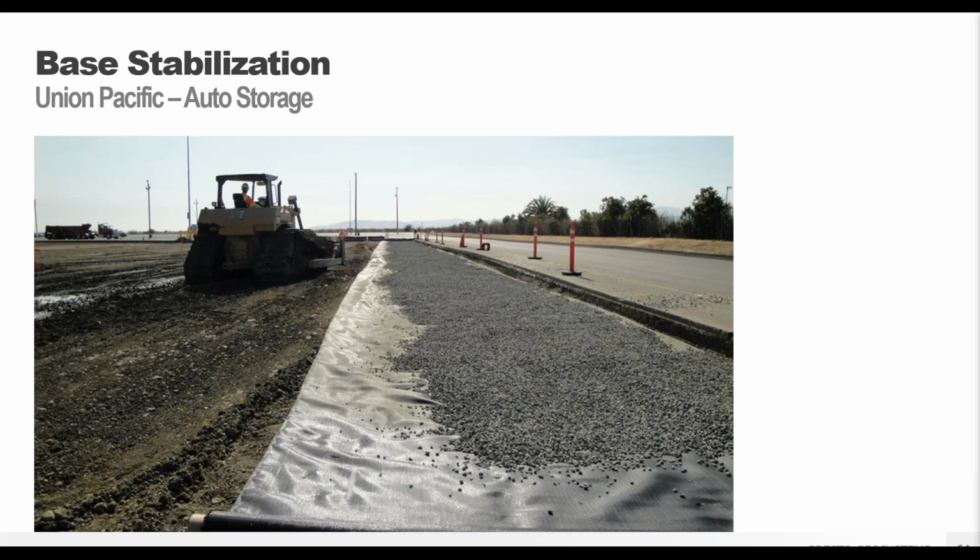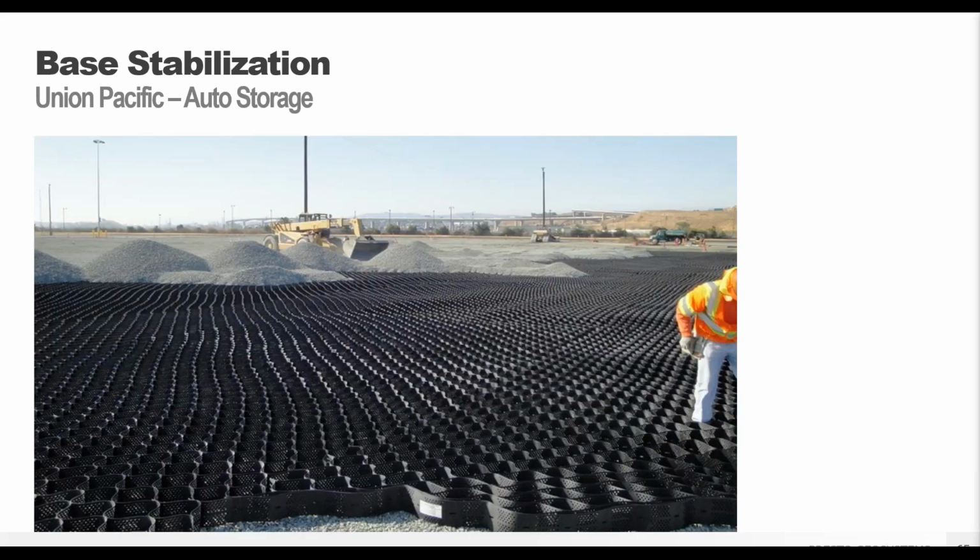So the base layer provided some additional load support, but also an area for water to move underneath that final asphalt surface to help prevent pore pressure buildup. So this was definitely something they wanted to keep in mind. They knew that the area was very wet and soft. They didn't have any dewatering capabilities. So having this open graded base course allowed for free water movement without causing heave up into their hard surface asphalt pavement.